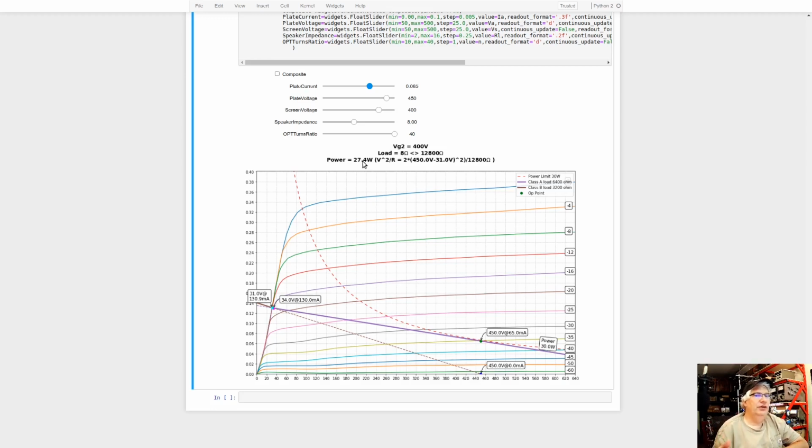The advantage of using pentodes in push-pull is that you can go to class B. Now, class B has a unique feature about it that class A doesn't. Class A, you want to be underneath power dissipation at all times. And this green dot right here is the one you want to have 70% lower. That's the recommended kind of bias point in the ballpark. So we don't want to run it that high.